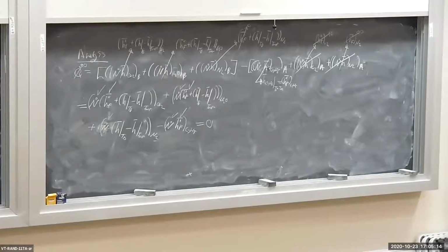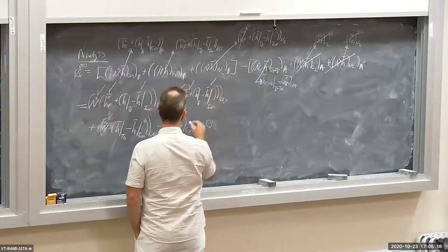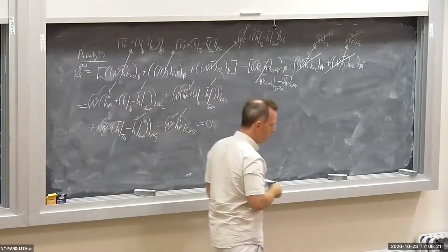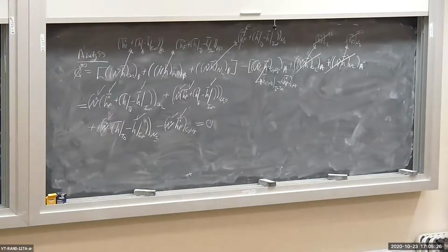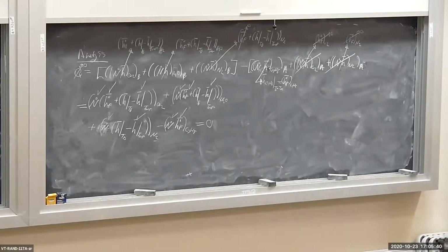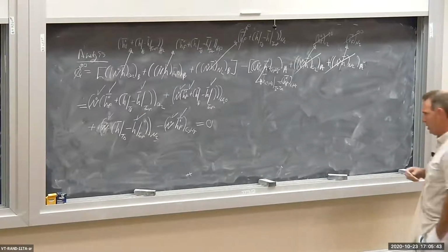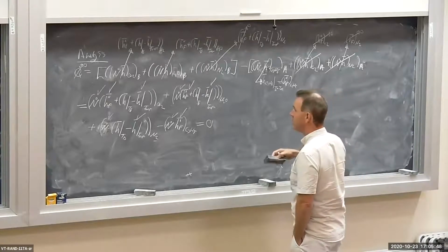Okay, so now in this equation, I have the H refs. So all I now have is a bunch of enthalpies evaluated at the exit temperature TB. The rest of the stuff is known. Okay, how are we going to solve this? Well, we're going to solve it iteratively. We're going to do a guess and a check, but we're going to try to do it intelligently.